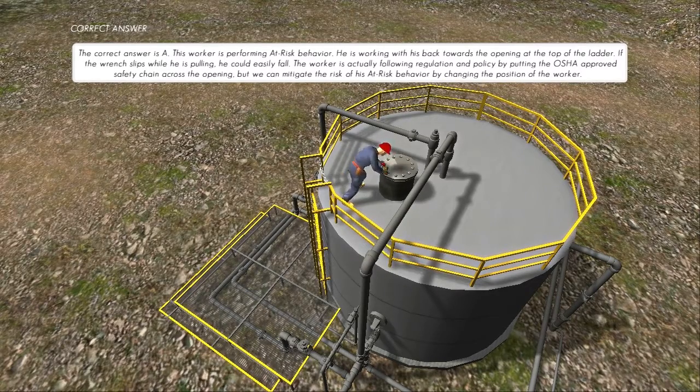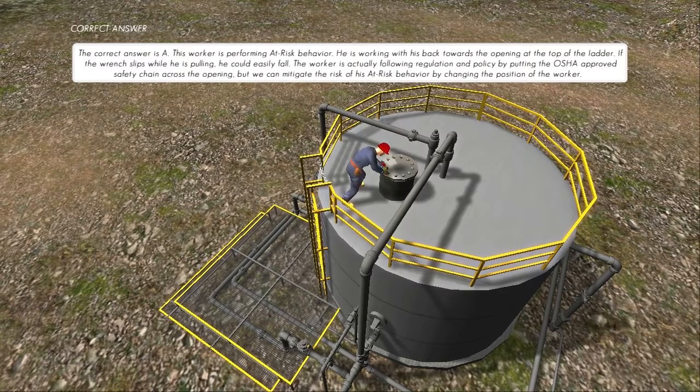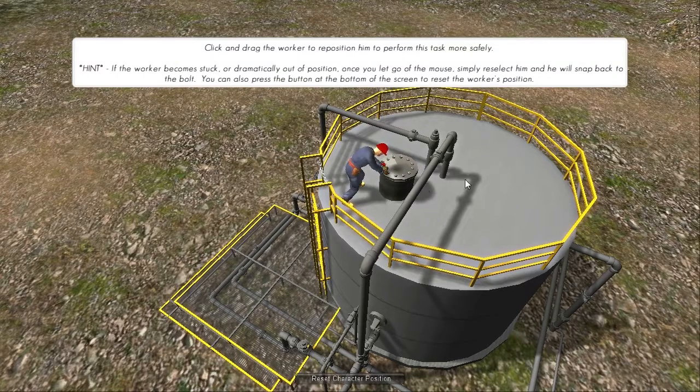He is working with his back towards the opening at the top of the ladder. If the wrench slips while he is pulling, he could easily fall. The worker is actually following regulation and policy by putting the OSHA-approved safety chain across the opening, but we can mitigate the risk of his at-risk behavior by changing the position of the worker. Click and drag the worker to reposition him to perform this task more safely.